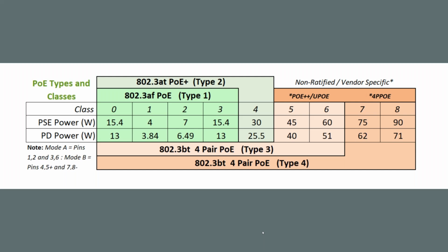Now there are a couple of types of PoE. There is passive, which means the voltage you send is the voltage you will receive, or there is the IEEE standard of 802.3 compliant. That's important because a compliant device requires a handshake to receive that power.